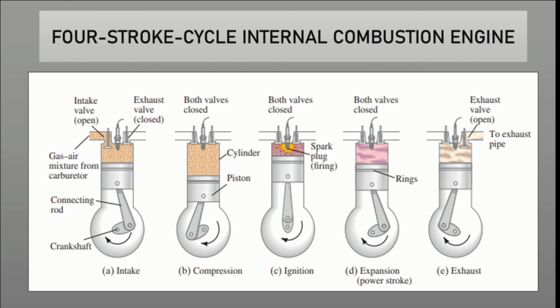In this stroke, the intake valve must be in the open position while the piston pulls an air-fuel mixture into the cylinder by producing vacuum pressure through its downward motion. That is what happens inside the intake stroke.